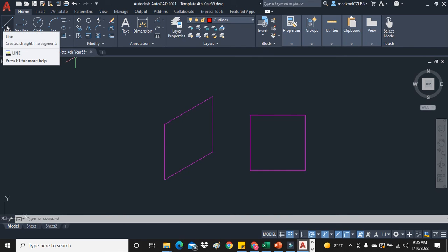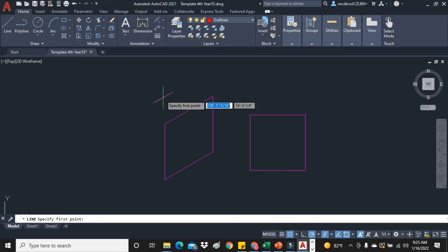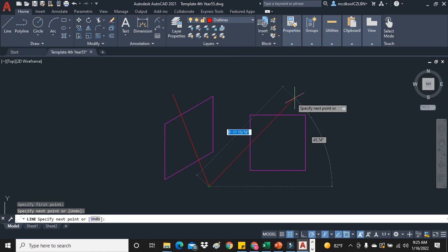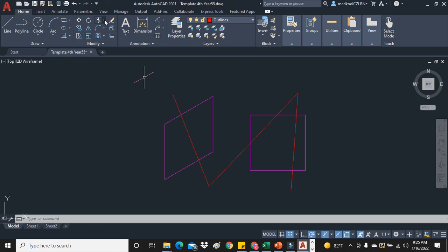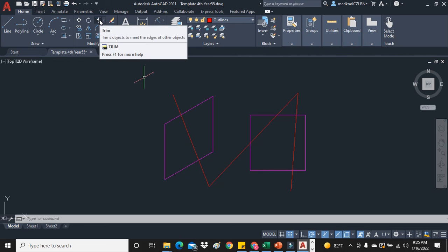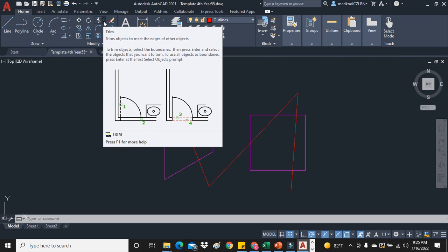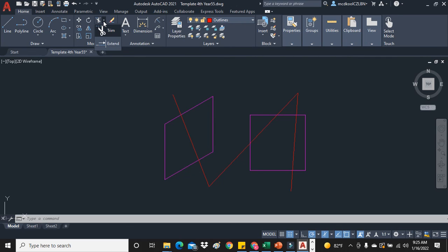And this is the last thing that we'll do in this video, which is to trim off areas. So I just drew in these three random lines. Suppose I wanted to keep a part of this line in here. So I select my trim tool, which is the scissors. This is going to be used to cut the actual lines. So I press the down arrow.